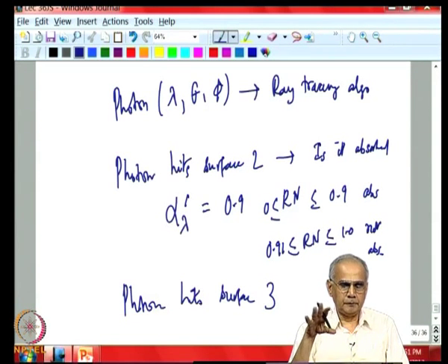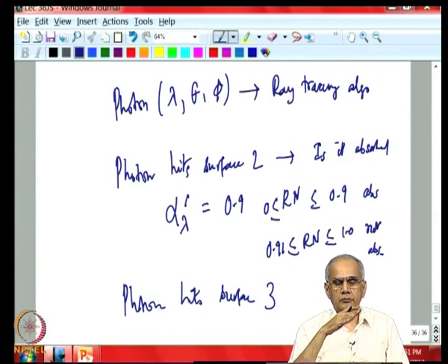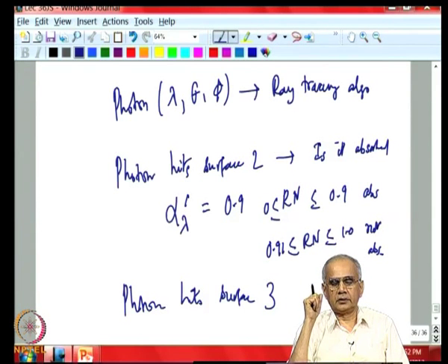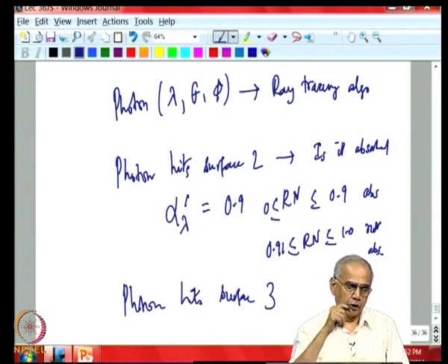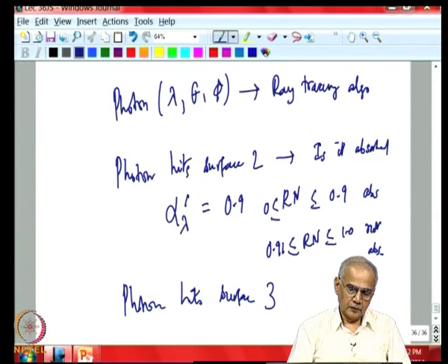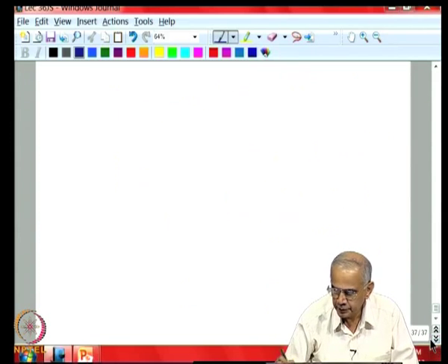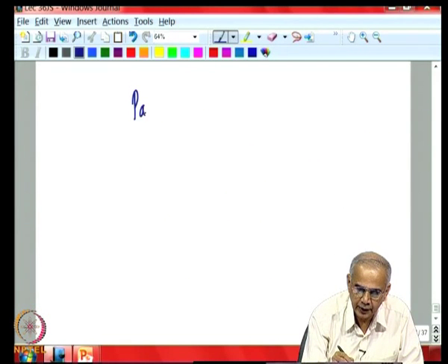This is very simple, and in many situations people write their own software to calculate a shape factor using Monte Carlo. But when you deal with a participating medium, life gets a little more complicated.